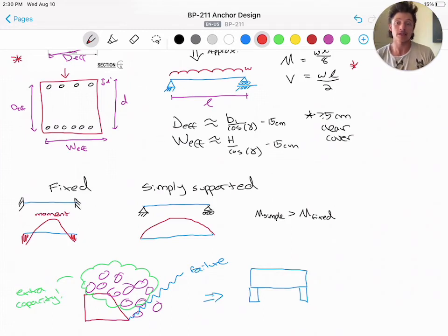But first I want to address what about ramp fill. And I've added in a diagram here to explain. Due to the unknown difference in stiffness between the ramp walls and the ramp fill, which was discussed in the previous sections where we dove into the ramp wall design more, we don't want to assume that the load transfers evenly across the surface. So we'll perform the analysis assuming that the ramp fill does not contribute in both flexure and shear, but support from flexure and shear can be added later if you find that these checks are not passing.